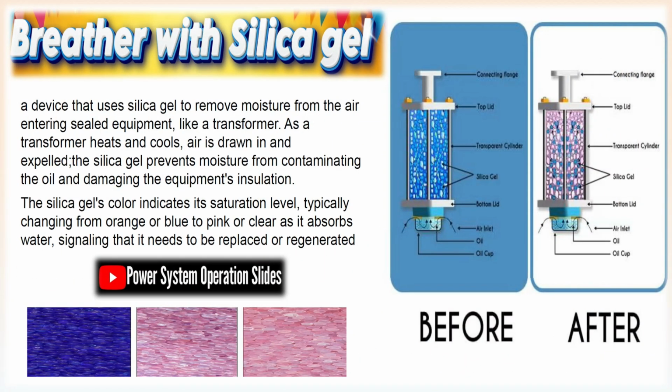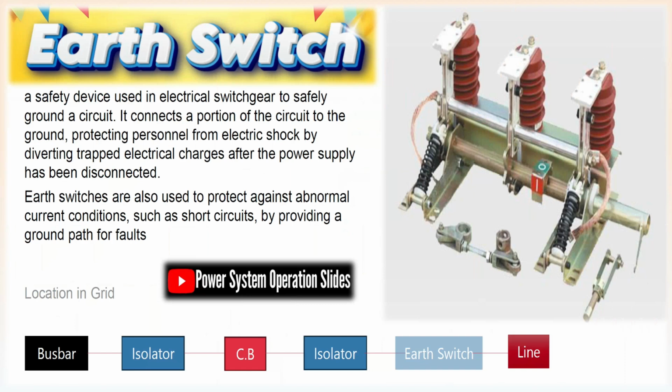Thermometers and thermal relays. Thermometers provide passive temperature indication, while thermal relays actively trip equipment under overheating. Thermal relays protect motors and transformers by preventing thermal damage. Both enhance monitoring and safety.